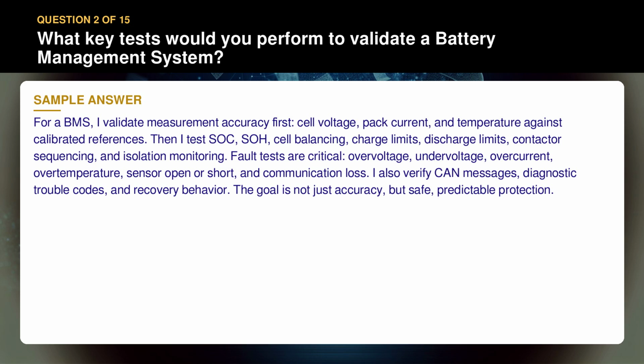Fault tests are critical: overvoltage, undervoltage, overcurrent, overtemperature, sensor open or short, and communication loss. I also verify CAN messages, diagnostic trouble codes, and recovery behavior. The goal is not just accuracy, but safe, predictable protection.